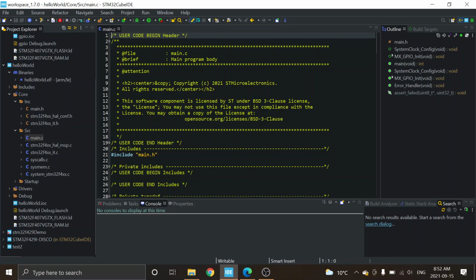Okay, that's the one that gets me. I put my code in the right place, but I include something and just tuck it in after that, and then things work great until I add something, and then all of a sudden I'm getting all sorts of errors and going, what's going on? And it's because I stuck include math.h here and not between the user begin includes and user end includes, which says don't wipe it out when you go change the graphical environment. Okay.